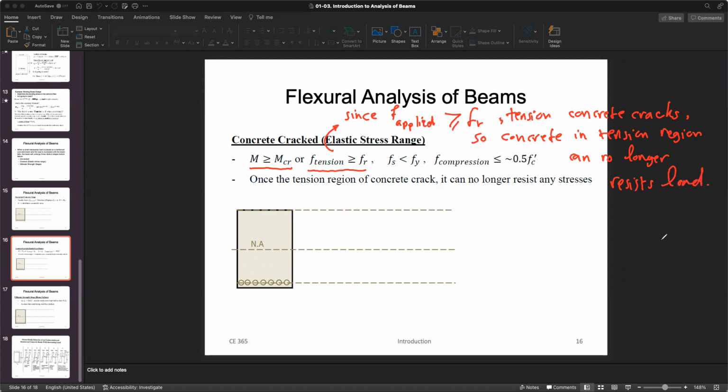All right. So let me tell you what's going on here quickly before I go back and show you the strain and stress distribution and the elevation of the member. We discussed that on the top we are dealing with compression, and tension at the bottom. As soon as you crack, on which part of the concrete will you crack? Well, the cracking is going to happen here, on the tension side. Why? Because it is weaker. That is a vulnerable place in concrete, tension. So it starts to crack, okay?